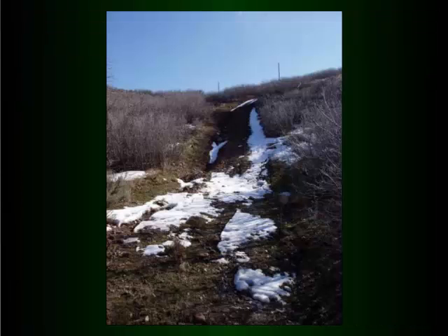This just, to me, would be a skid trail. In this particular case, it's some kind of a trail on the base here, and a pretty deep rut in it. Good place for a water bar. Kick the water off that so it doesn't continue to rut down it.